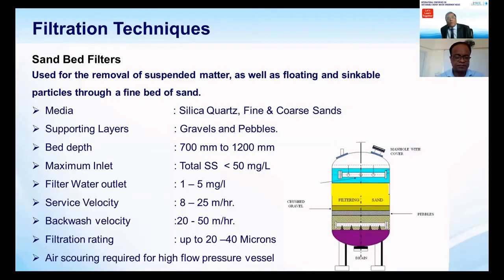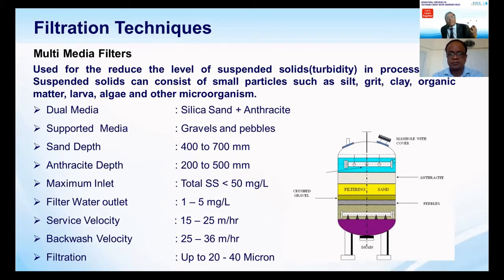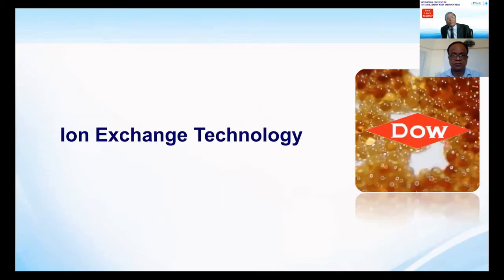About the sand filter, how to design the sand filter, you will get the idea, multi-layer there, how much velocity we have to get, and what size of particle they remove. And this is a multimedia filter. You can see it has multiple medias that depend upon the application, that what we have to do with that.